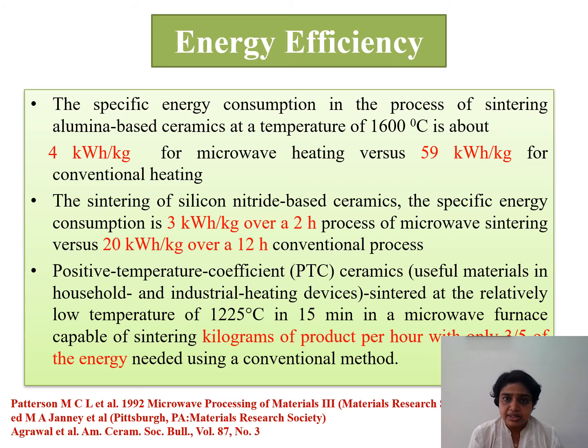Similarly, there are other numbers also, for silicon nitride based ceramic. The specific energy consumption is just 3 kilowatt hour per kg for 2 hours in microwave sintering, against 20 kilowatt hour per kg for 12 hours in conventional methods. And then we come to the PTC ceramics that are useful in household and industrial heating devices.